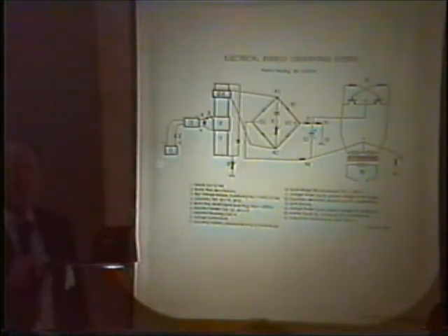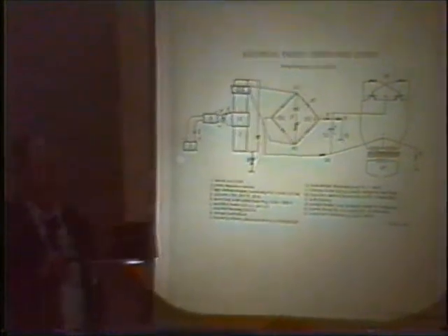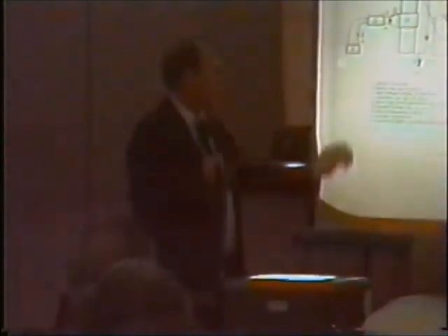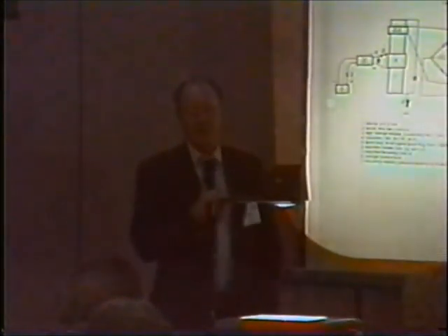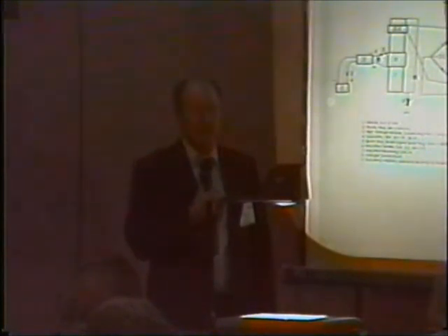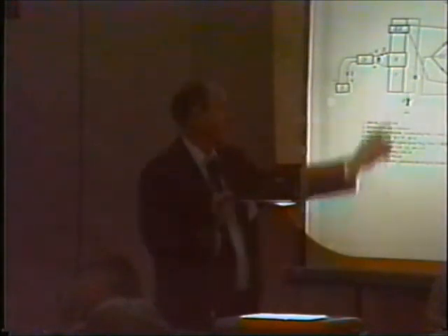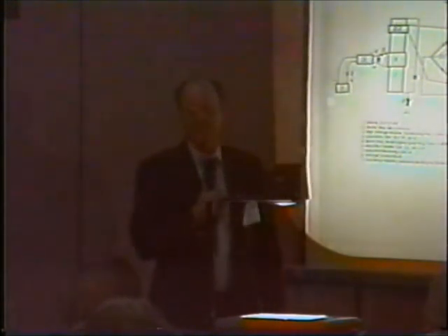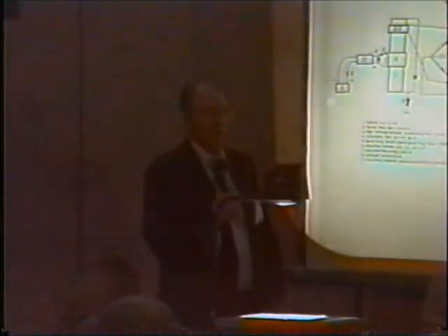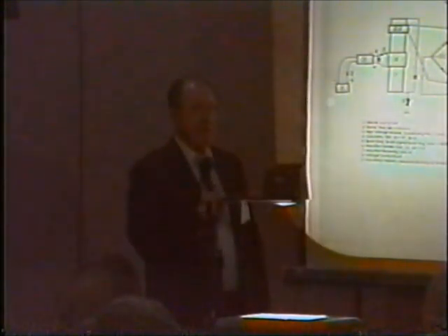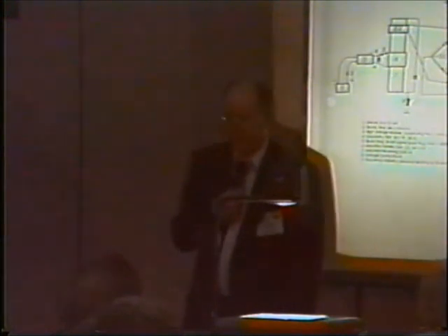So needless to say, I've gotten pretty good at finding the surplus ones. I burned a lot of them up figuring out how to get things done, and this diode here was one thing that pretty well saves me. It prevents kickback, which destroys your high voltage laser module. It's on your plus side outlet of the battery. It does something else very interesting also.